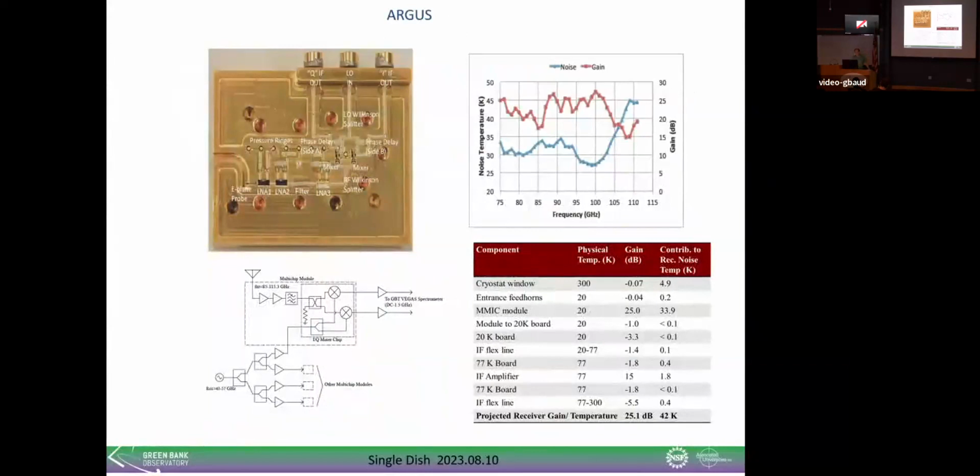The difference I'll point out is that due to the bandwidth, you have to inject the LO within the bandwidth. That requires an IQ sampling scheme. In order to get the upper and lower side bands from this receiver, you have to take I and Q channels and combine them to select the upper and lower sideband. With our other receivers, we just LO down convert, and we don't have to worry about that. But this one, due to the bandwidth, had to include the mixer along with the low noise amplifier in the module, because the LO was injected inside the band.